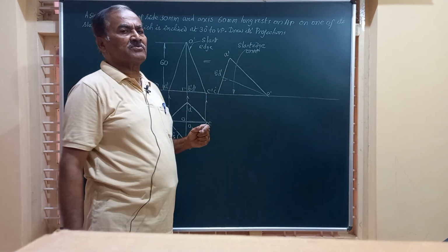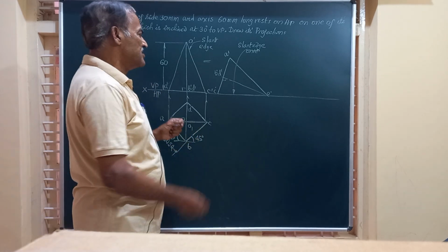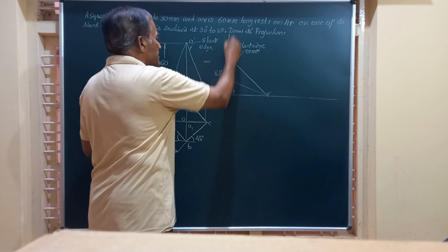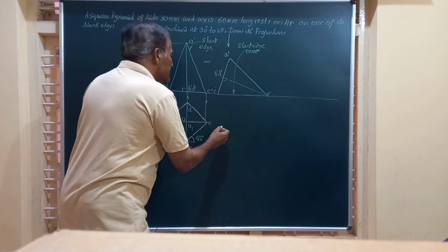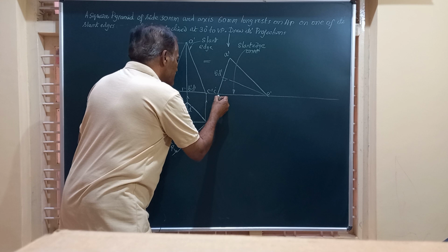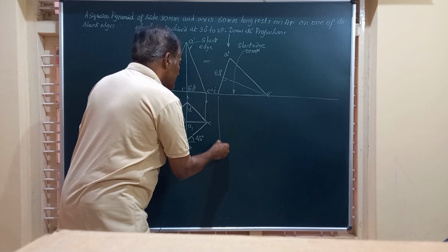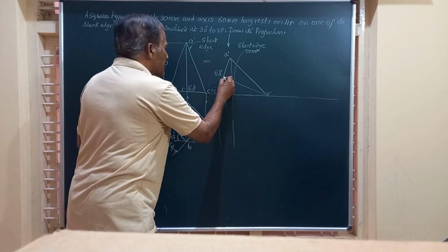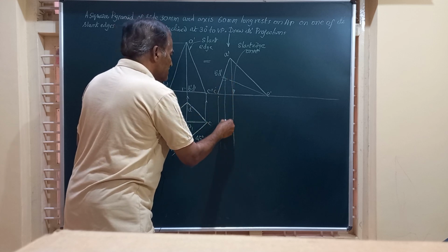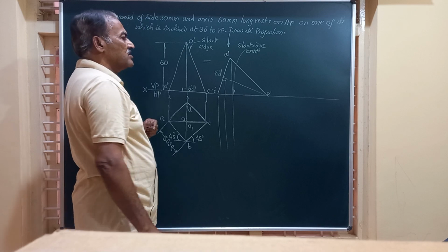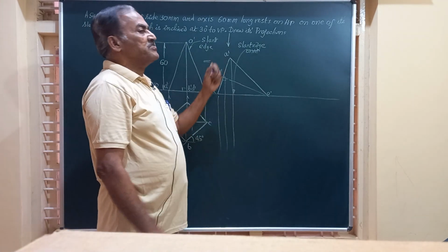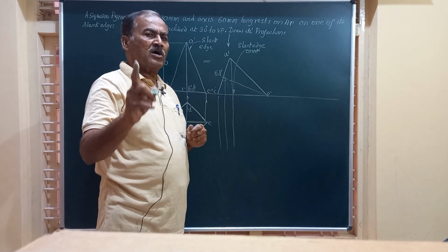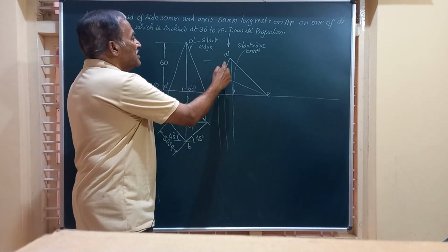All the dimensions of the edges and that of the base remain the same. Now friends, I will just look at this object from the top and write down the corresponding top view. So friends, I will draw a line through all these, a line through these, and another line through the center here. Friends, when you look from the top, for all the cases of pyramids and the cones, the complete base